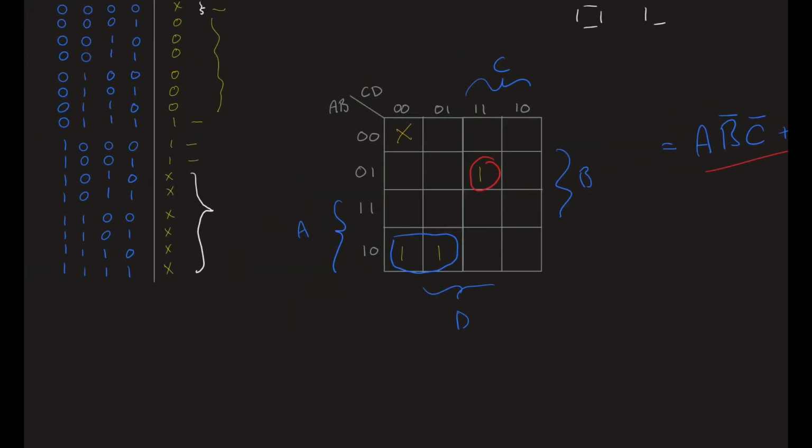But if we really don't care what the value is, we can do better. Because right now we're forcing it to be 0. We're saying it has to be 0. Instead, what do we got here? 1, 0, 1, 0. That's here. I don't care. 1, 0, 1, 1. Don't care. 1, 1, 0, 0. Don't care. 1, 1, 0, 1. I know it's harsh, but I don't care. 1, 1, 1, 0. Don't care. All ones, don't care about you either.